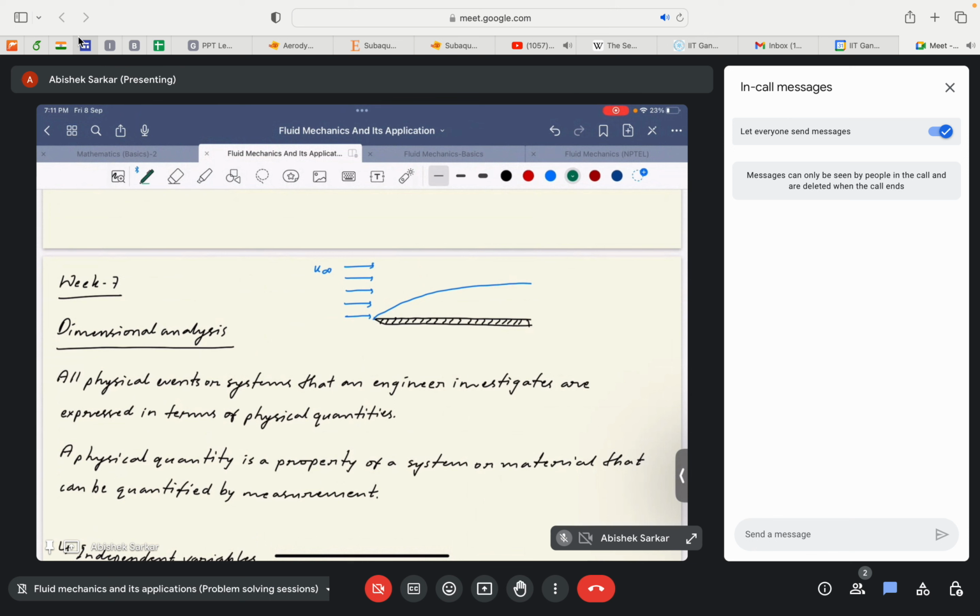To make the concepts easier to understand, we can say this boundary layer divides the flow into two distinct layers, where the region within the boundary layer is a viscous region. The region above the boundary layer is an inviscid region, or more popularly the potential flow region.